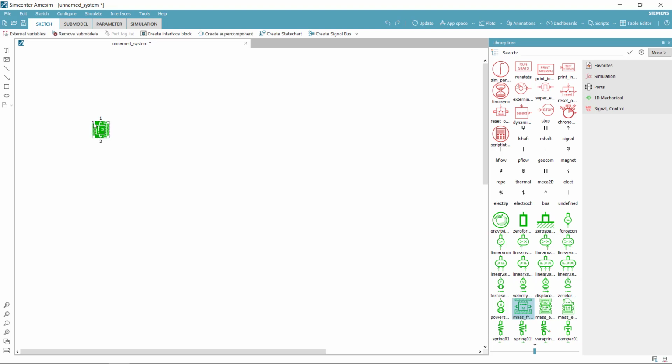If you would like to change the position of any components, you can select components with a left-click and hold to drag components and reposition them. Place the component by releasing the left mouse button. To reorient a component once it is placed, double-click the component icon, and once again, the middle or right mouse buttons can be used to flip or rotate the component. Left-click to place the component.